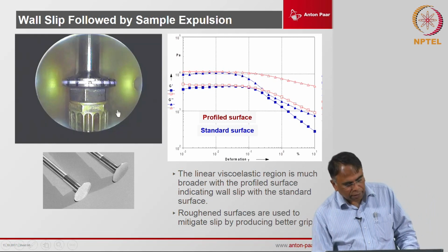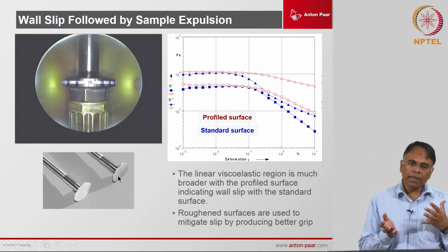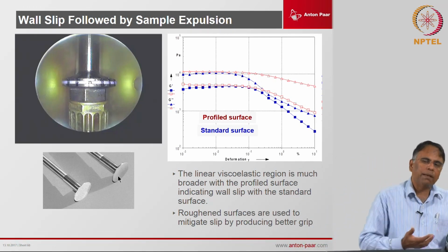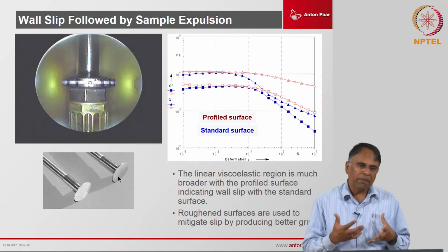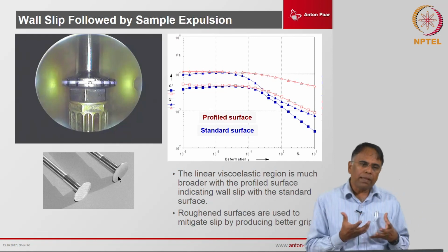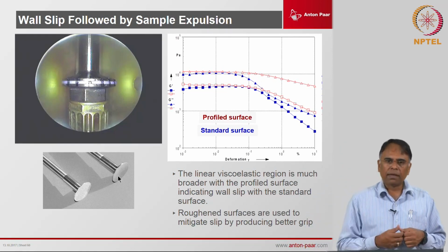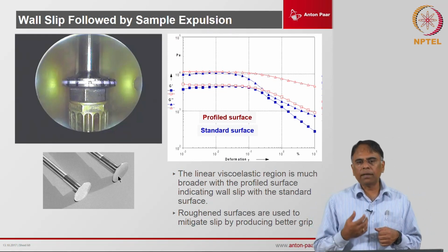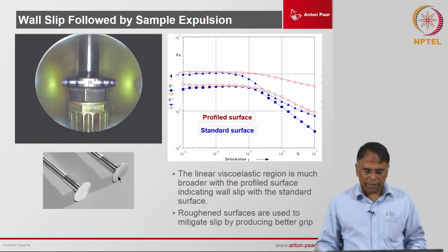So, to counter that we can use geometries with surfaces which are roughened in a certain way. The roughening can be done by sandblasting, or it can be done by profiling, okay. So, if you have very slippery gels, then profiling is good, but if you have very tough viscoelastic solids like rubber or asphalt at low temperatures, then we can use sandblasted plates over here.